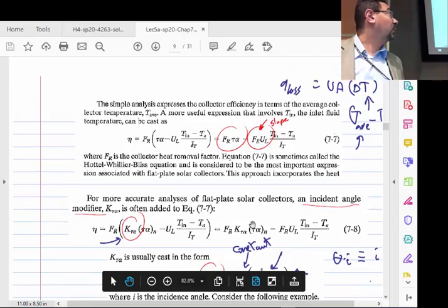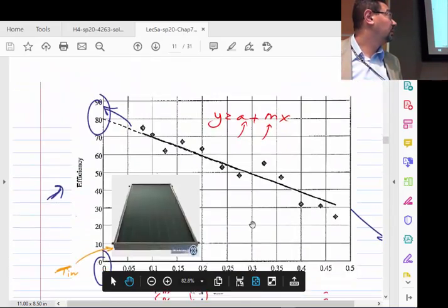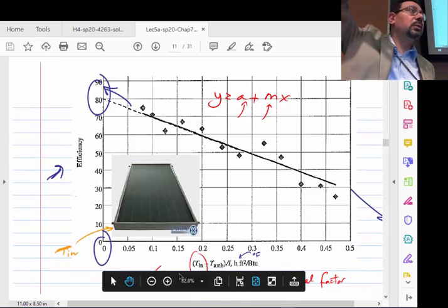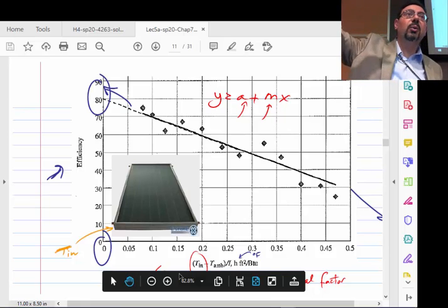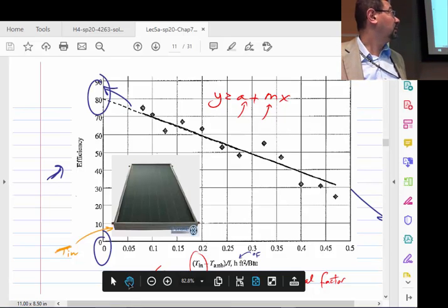Very good. So now, like you can imagine, they do those tests in the lab, right? They can put the sun, not the sun, they put like light or stuff that is exactly 1 sun, 1 kilowatt per meter square, and they keep calculating; you can measure the water outlet. They can just measure the temperature, and therefore they will be able to calculate that efficiency.